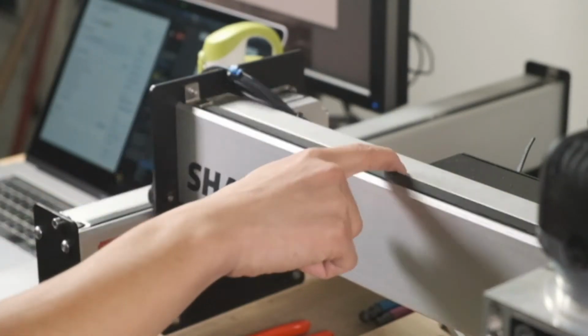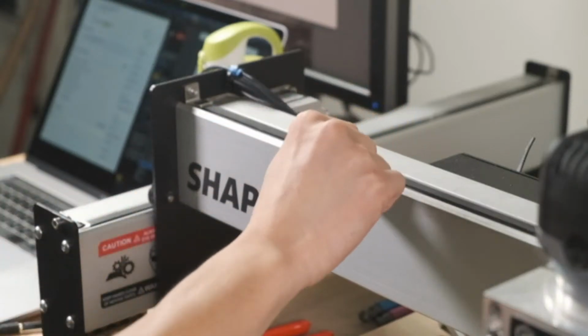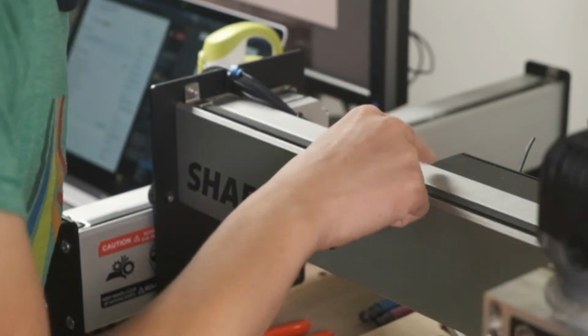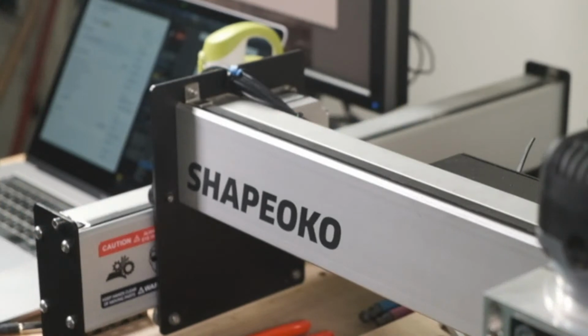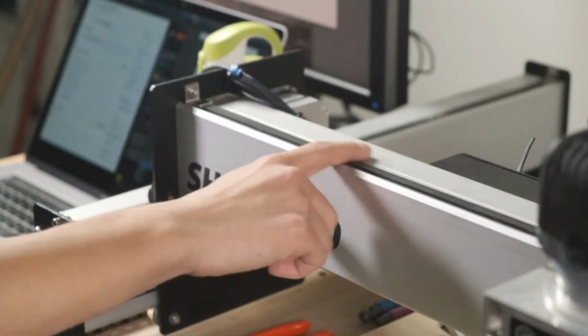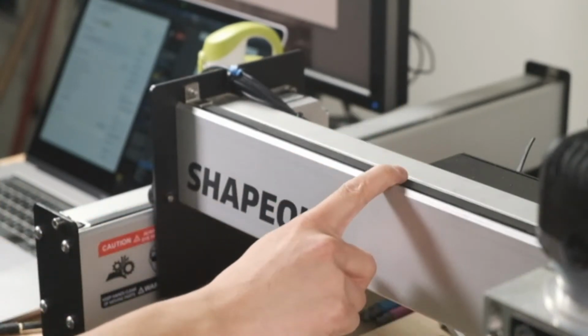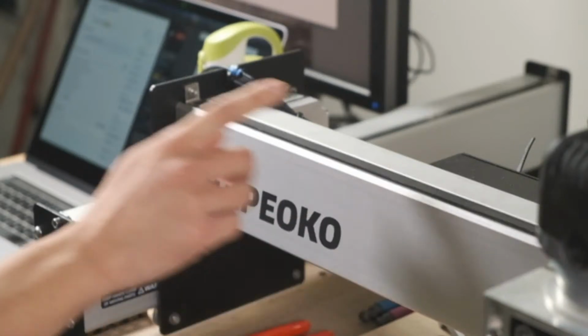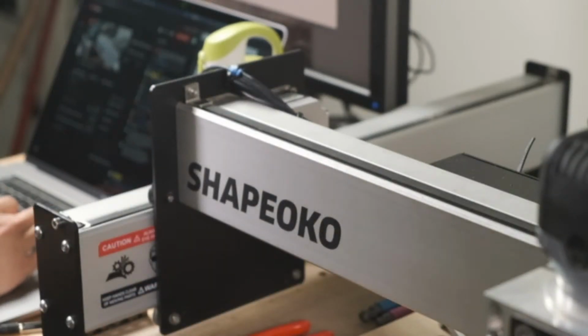So that is tensioning the belt to an appropriate point where it's now slapping the rail. And it shouldn't allow any slippage or backlash. So let's talk about some other issues. Let me actually check the chat.